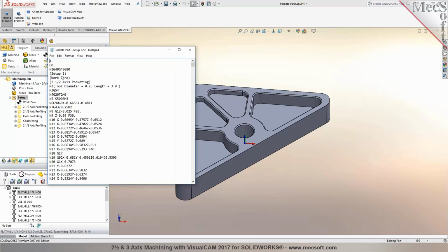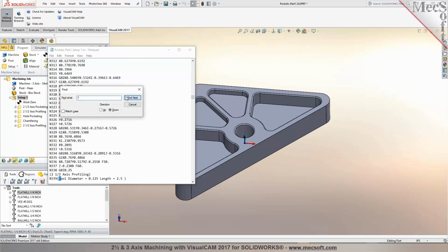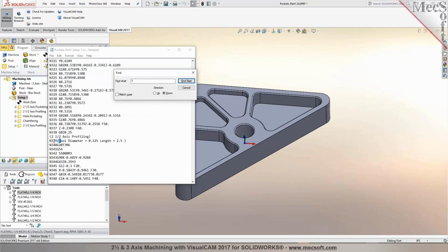Now the code text file is already prepared, an NC file. It has the work offset number, your tool number being called, your tool height offset. And then there's your code, and also output tool numbers. When you do a search for a tool, the next tool number, you can see changes to tool diameter of an 1/8 inch.